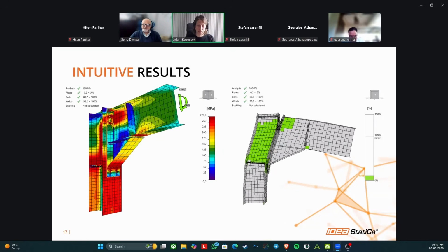And this is great, because you get a picture of what is going on in this detail of your structure, and you as a designer can react to that. For example, here you can see the concentrations, you can strengthen the bolt assembly here or whatever, and on the other hand, you can maybe use fewer bolts here to have your design optimized and economical. That's a great thing.